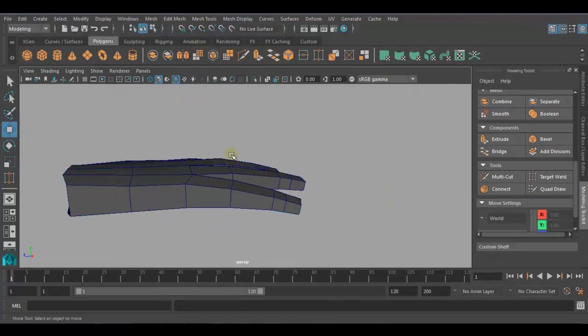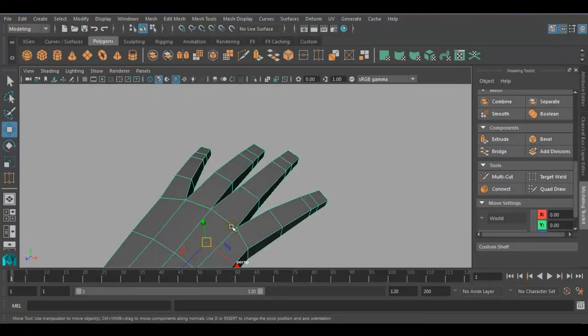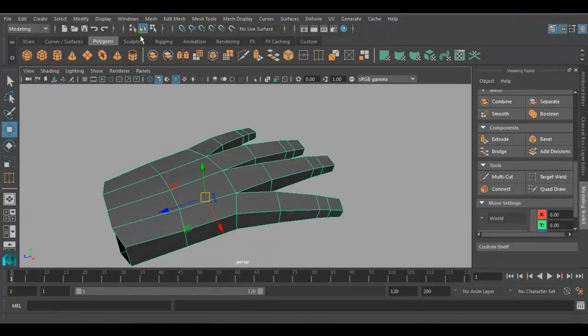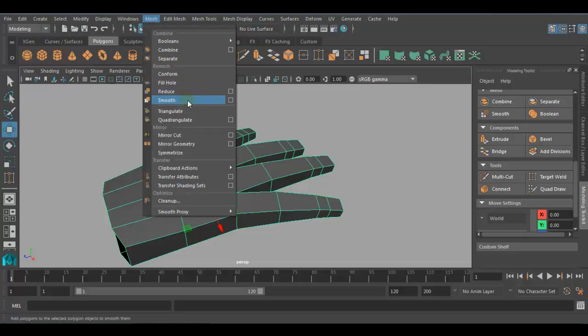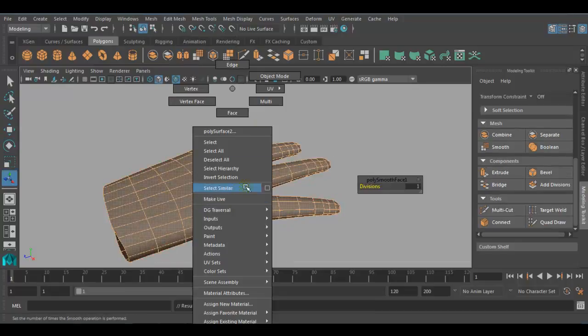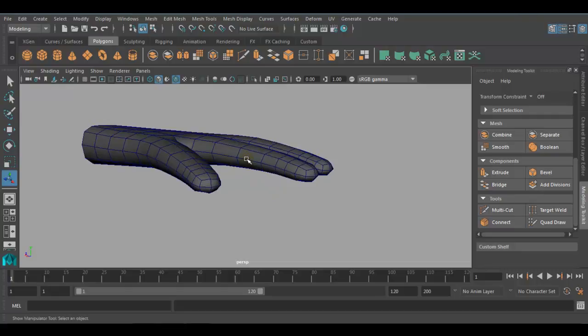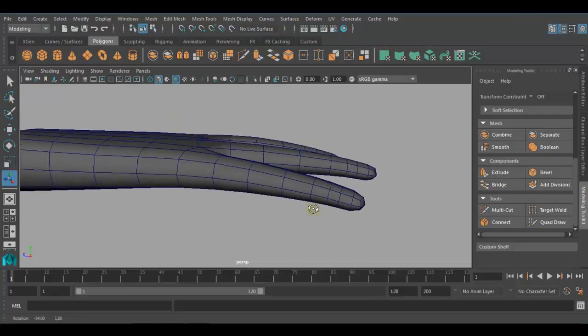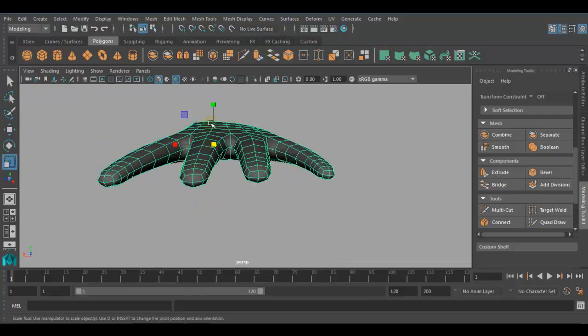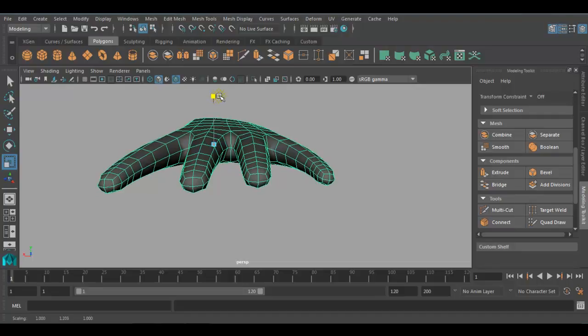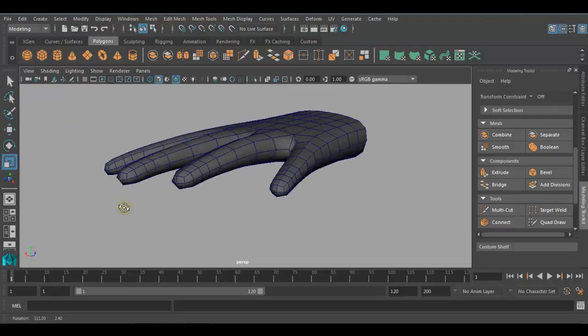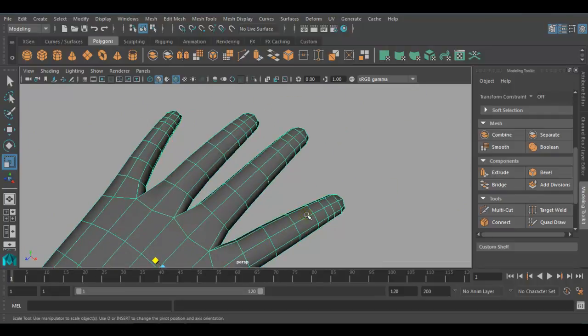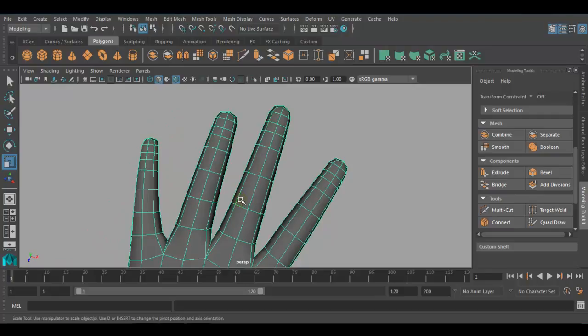Right. Now, as we know that we have created the basic shape over here, go to mesh, apply smooth. It will double the existing subdivisions. Click, and you can see over here we have got this particular shape for the palm and a round shape for the fingers. You can add a little bit of scale to have a wider, you can say thicker, shape. Fine. The next thing is adding nail details, adding the details for the fingers.